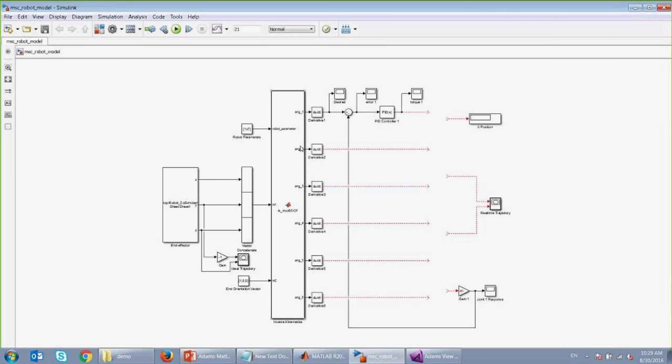As you can see here, from joint 2 to joint 6, we're just taking a derivative of the angular displacement and getting the angular velocity. So we're using the angular velocity to control the movement of the robot. But for joint 1, we're actually adding a feedback control system, and we constructed a PID control, so we're using the torque to manipulate joint 1 instead of the velocities, because sometimes the torque is more commonly applied in real robot design. So it all depends on your requirements.